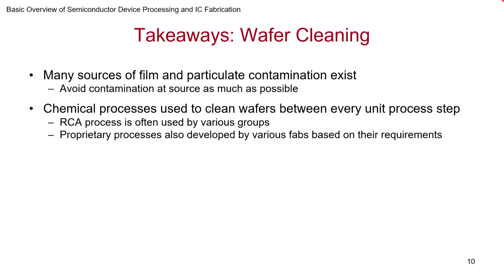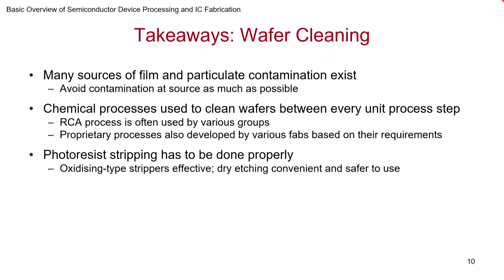RCA process is one of the standard processes that is available, and proprietary processes would be developed, and maybe you in your lab also may have your own specific process, because you know what is your main source of contamination, and you may want to emphasize on that and make sure you get rid of it.